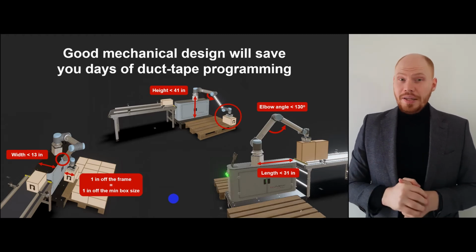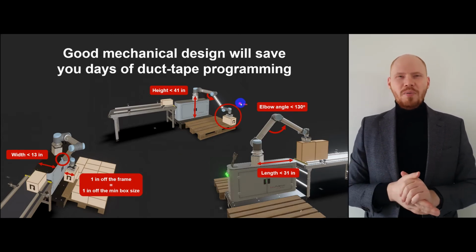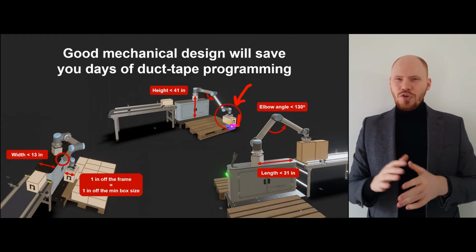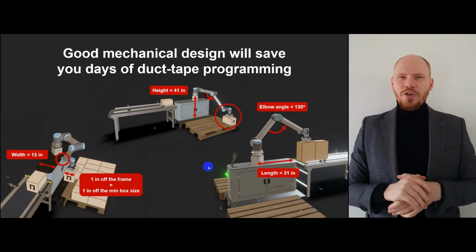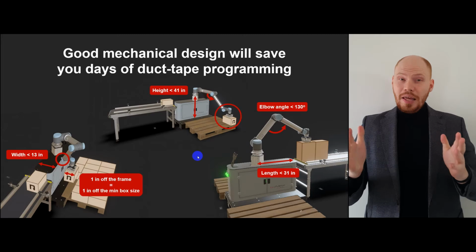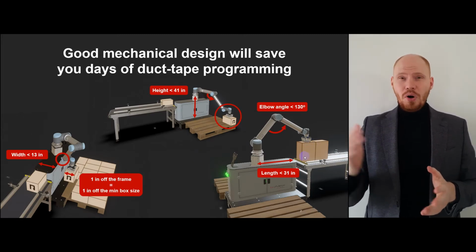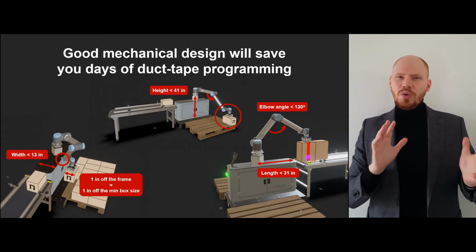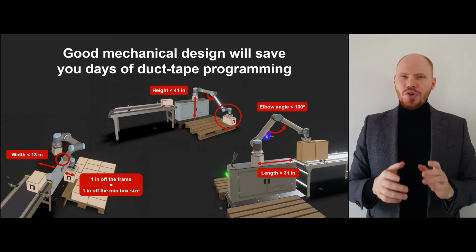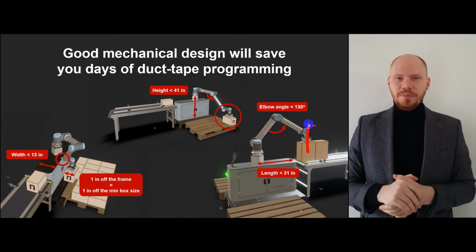Next parameter is the height in the home position. This will impact reachability of your robot and also the minimum height of the boxes you can palletize. In general, the height in the home position should be below 41 inch if you're working with a UR10 series of robots. Finally, the length of your frame. It will impact the maximum height of the box you can pick. As a rule of thumb, you want to keep the elbow angle below 130 degrees. This usually becomes a constraint when the robot lifts the box from a conveyor.